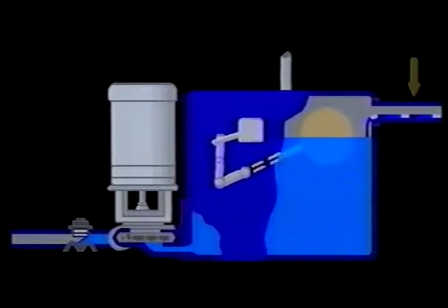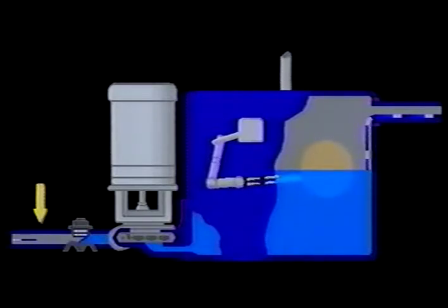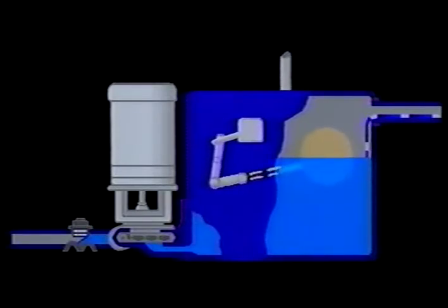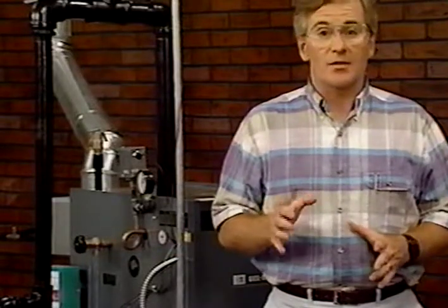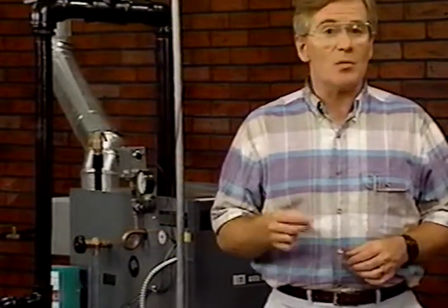When the low water cutoff cycles off on low operating water, the condensate discharges from the receiver into the boiler until the low water cutoff is satisfied that it has a safe boiler water operating level. The addition of a mechanical condensate return system can be rather expensive and not generally used for a typical residential steam boiler installation.